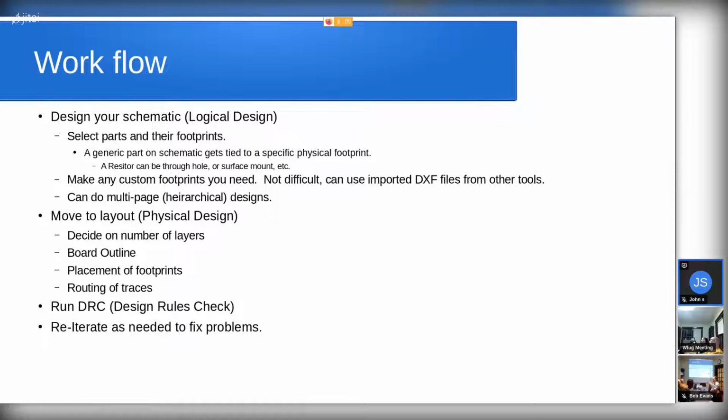When you shrink those chips down, you have either the SOIC, which is surface mount with little legs coming out, or ball grid array, where they just have little balls on the bottom of the package. You have to put the paste down, put the chip on top, and then heat it up either with an oven or a hot plate to reflow the solder. With ball grid arrays, especially once you get up to 3,000, 4,000, 5,000 balls underneath,